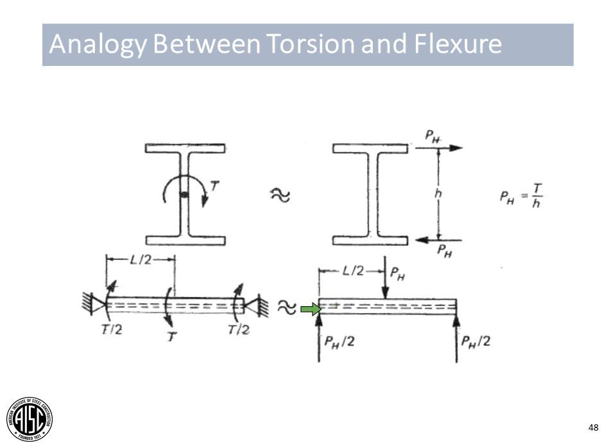For simplicity, you could look only at the flange dimensions to look at the flexural strength of the flange itself, or you could include perhaps up to a third of the web in the resistance to that lateral force.